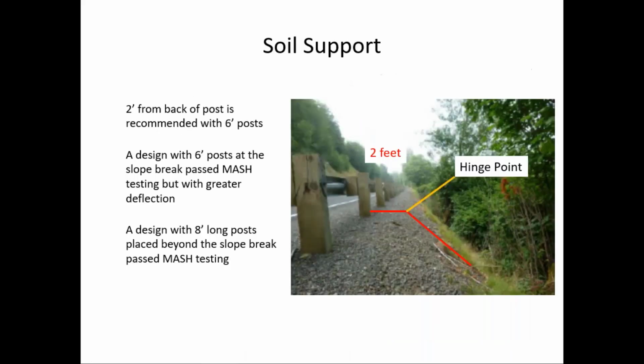Also, soil support is important. It's recommended that there be 2 feet from the back of the post to that hinge point if you're using 6-foot posts. And it mentions that a design with 8-foot long posts placed beyond the slope break passed the MASH testing criteria.